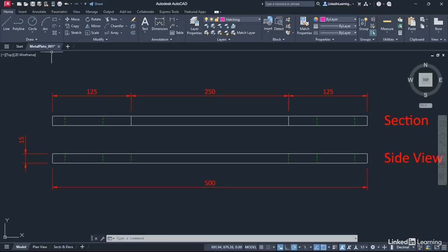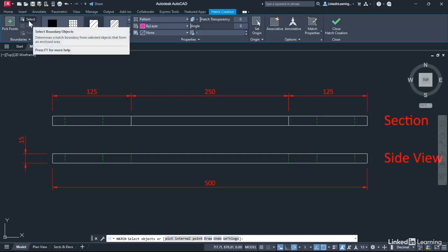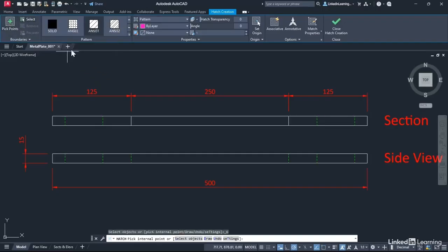So we go over to the Draw panel, Home tab on the ribbon, on the flyout there, and select Hatch. Now, we want this one here, ANSI 31, American National Standards Institute 31. It's a standard cross hatch pattern. Now, we're defaulting to select, you'll notice. Can you see that? Because we used that previously with our boundary command. Go to pick points, and then when you hover, it'll give you a little preview now of what your hatch pattern is going to look like. So with that hatch scale of 1, we're looking good.